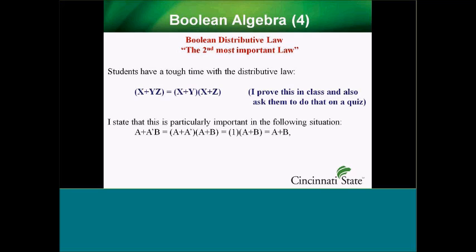Your answer is A or B. Well, there are no inverters. That's 1 chip. So just by doing this one step, you've reduced 2 chips out of 3. This is a little motivation to get them to understand, because they learn pretty quickly when they start wiring things up that it takes a while and it's very easy to make a lot of mistakes wiring circuits.